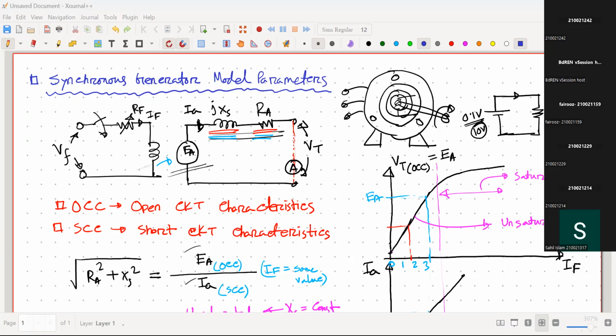That's why, in order to mitigate most of the reactive power consumed by inductive loads, we use extra capacitive load connected in parallel with those inductive loads, in order to improve our power factor. All of you know that from your previous AC circuit knowledge.